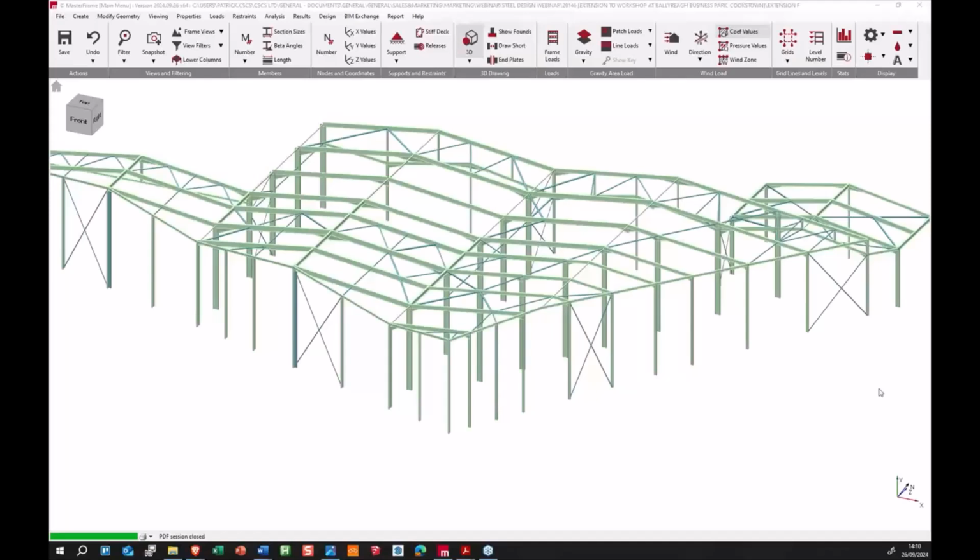That is traditionally more so used in the British Standard Code for sway only loading case, where the sway only case only has horizontal notional forces applied to it purely for the purposes of the calculation of the elastic critical load factor. So you can get a benefit really to reduce your elastic critical load factors by including a 10% fixity to reduce those sway deflections, which is obviously what drives the elastic critical load factor calculation.